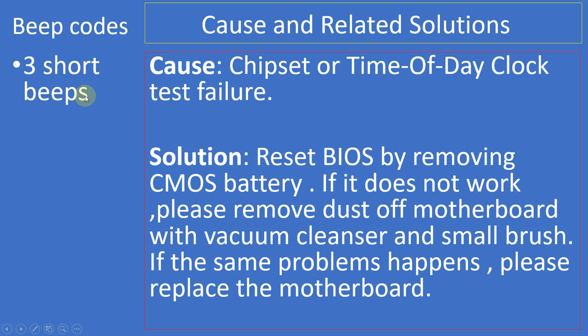Three short beeps. The cause is chipset or time of day clock test failure. So the solution is to reset the BIOS by removing the CMOS battery. If you don't know how to reset BIOS, search my video on how to reset BIOS and clear the CMOS. If it does not work, please remove dust off the motherboard with a vacuum cleaner and a small brush. If the same problem happens, please replace the motherboard.